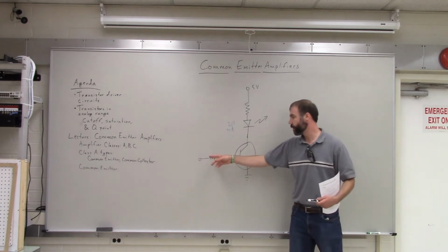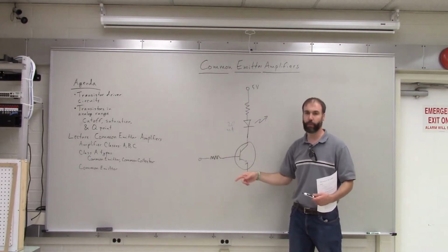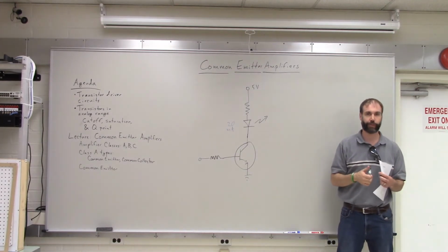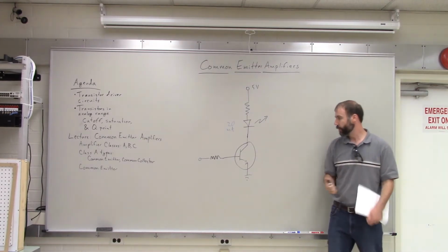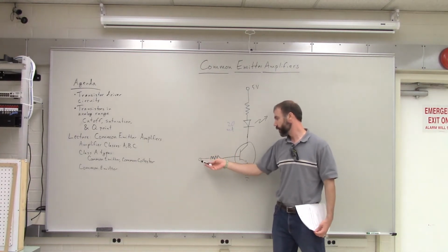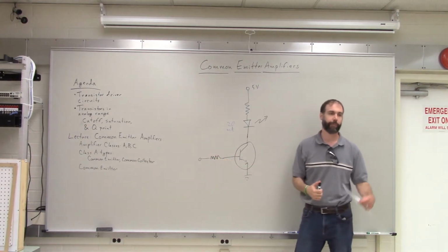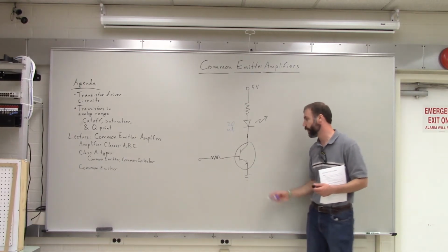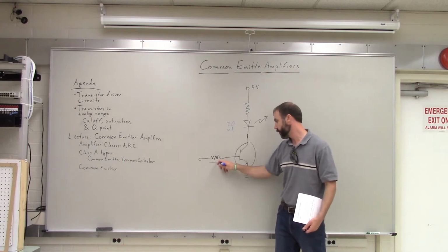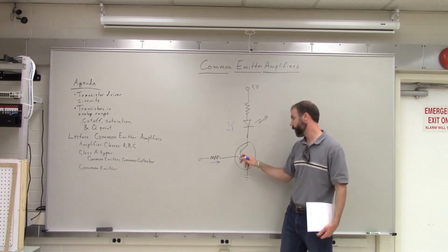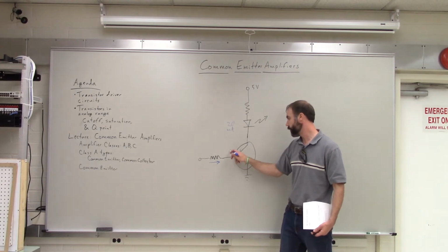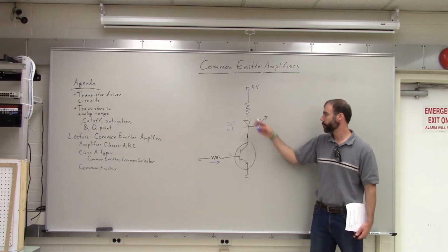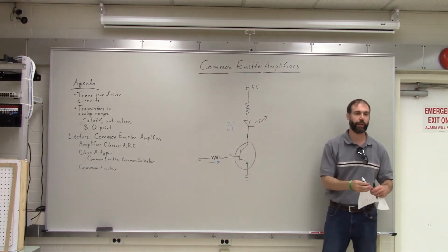Either we could connect it to the 5-volt supply when we wanted to, or we could have it connected to a square wave or some type of sensor, but it would be some control mechanism there. Okay? And then what we did is we figured out how much current we would need going into our base in order to achieve the 20 milliamps that we wanted through our LED.